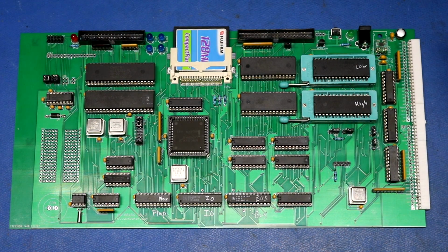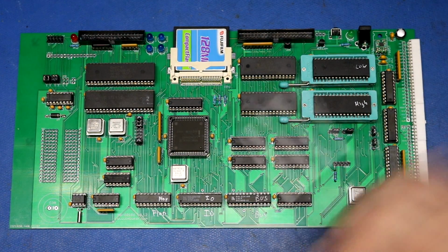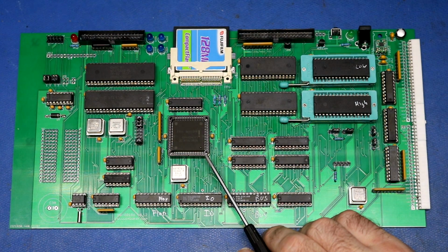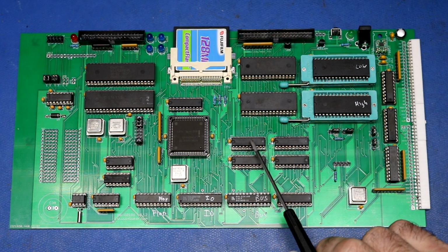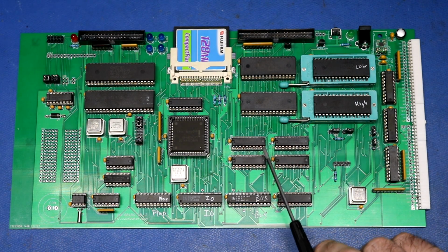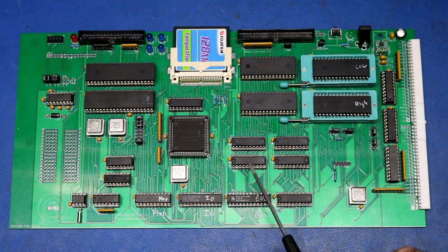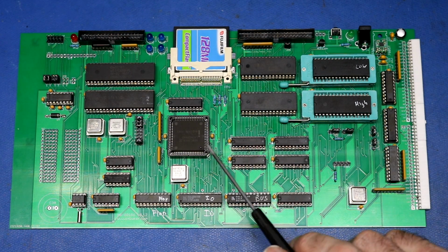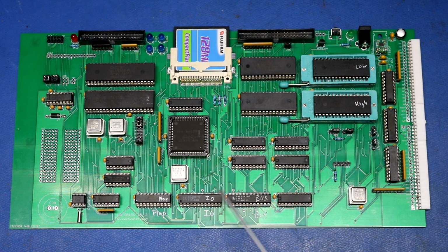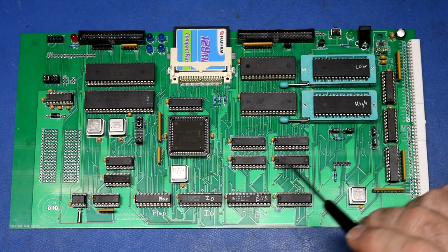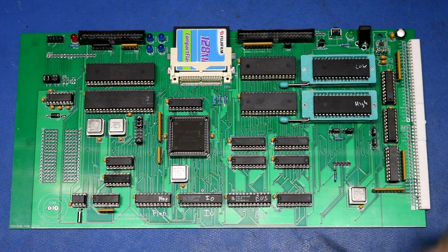Here is the H8 8186 CPU board. Right here in the middle, the square chip is the 8186 CPU. It's actually an ADC 186 XL-25, which should support a 25 megahertz frequency. Over here, we have the various address buffers and data buffers for the address lines and for the data lines. Remember, this is a multiplexed CPU, so the 16 AD lines are shared between address and data. And then we have our data buffers so that we can route those selectively to the 8-bit bus. There's also one down here for the control lines.